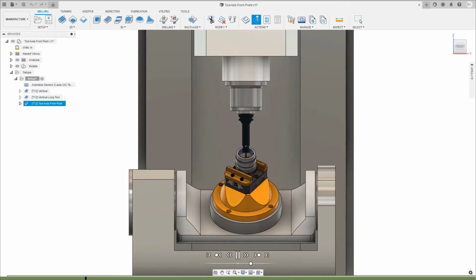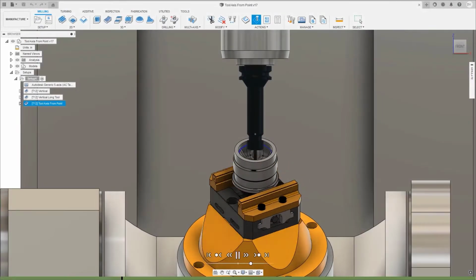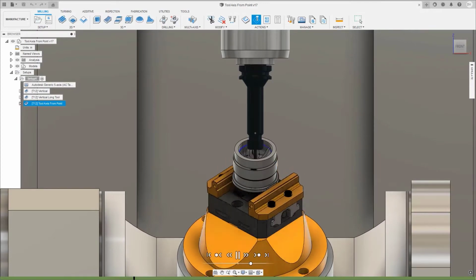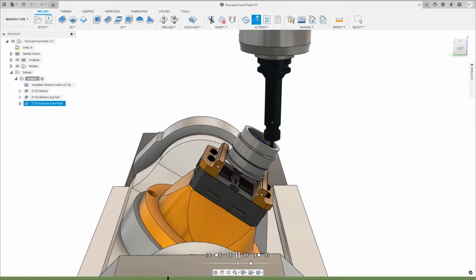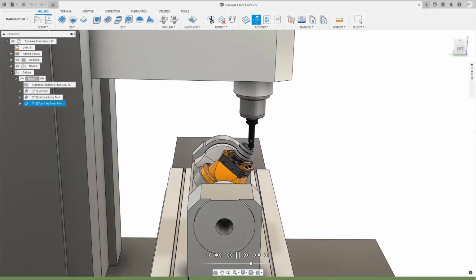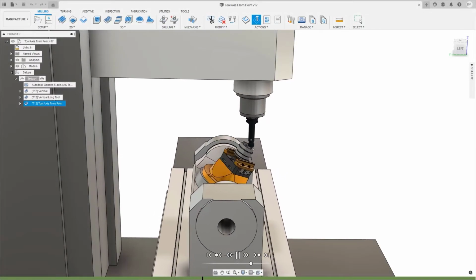The introduction of a 5-axis machine tool to your manufacturing process adds 2 additional rotary axes of control to the tool axis during the machining process. Using 5-axis machining can help minimize issues associated with multiple setups, poor cutting conditions, and interference with the machine or tool, which can occur during part manufacturing.